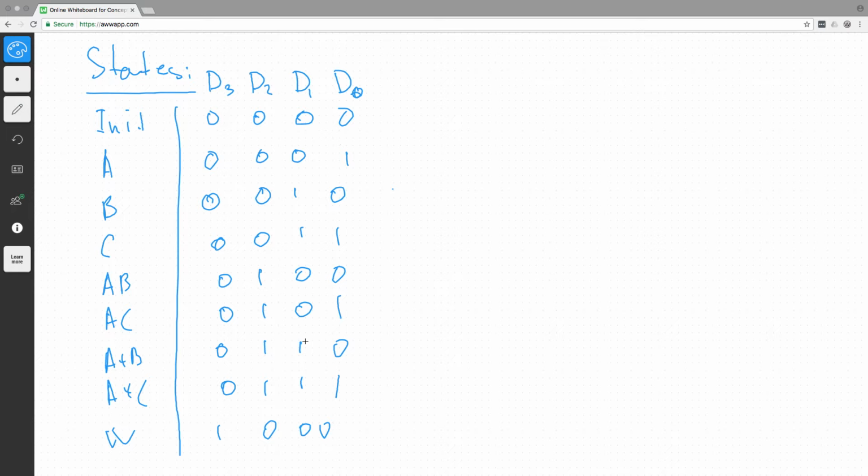What about other possible combinations achievable with the 4 bits? Those will be used for don't care, because we're not going to allow our finite state machine to have the remaining 7 combinations. So the remaining 7 combinations that are possible with the 4-bit presentation will be mapped to don't care. Now, let us consider an example of the excitation function.